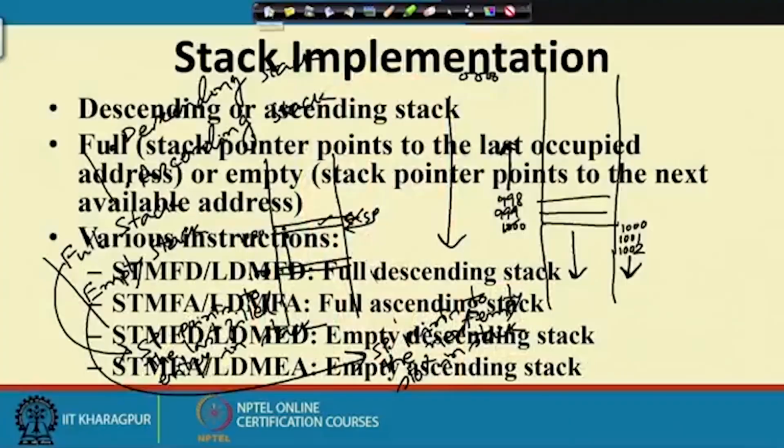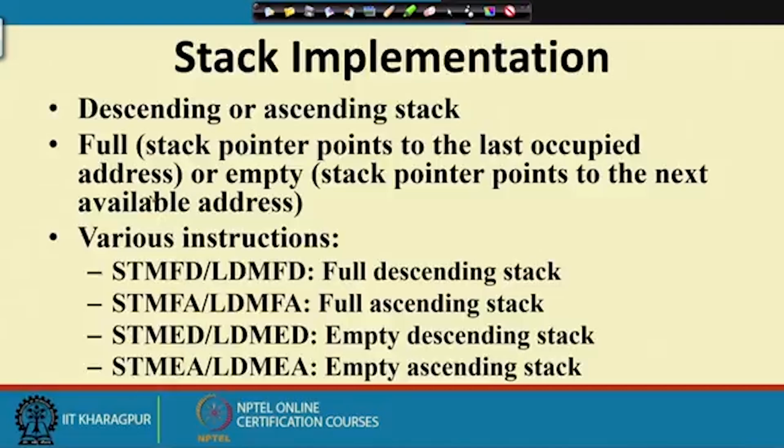On the other hand, if you remember 8085 or 8051, there is a specific rule: the stack pointer points to the empty slot, and the push operation should first increment the stack pointer and then the value should be copied. That means it has some sort of a full stack implementation, and the stack pointer was always getting decremented. So, it is a full descending stack that we had there, but the ARM processor will allow you to have any of the variants of the stack. Coming back to our discussion, we have got 4 different variants.